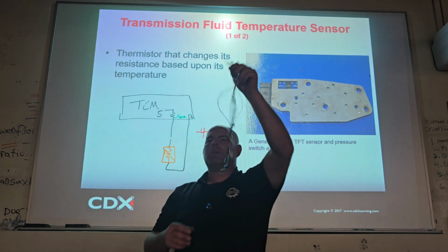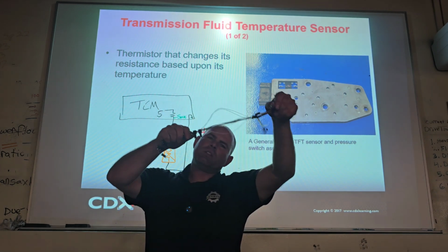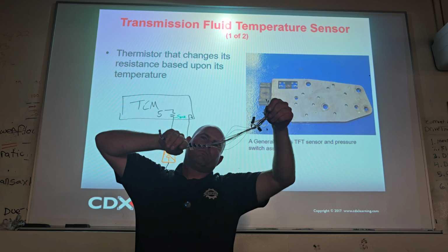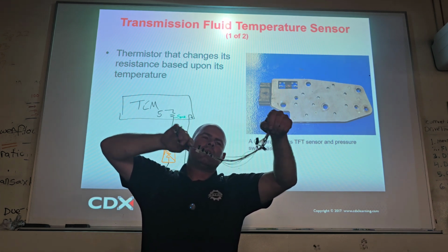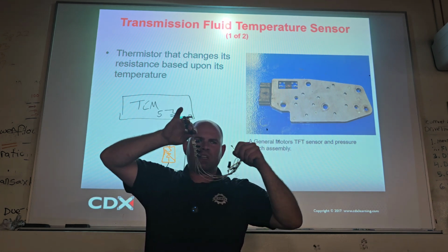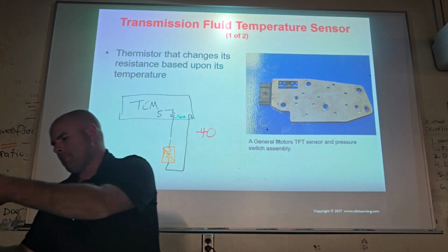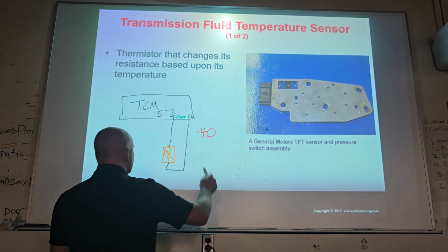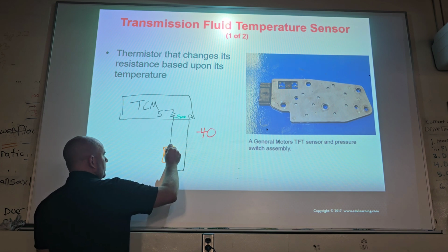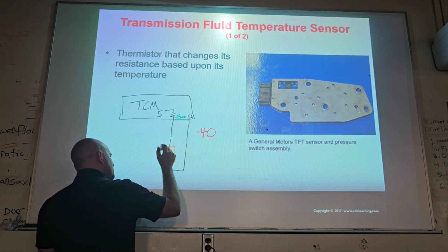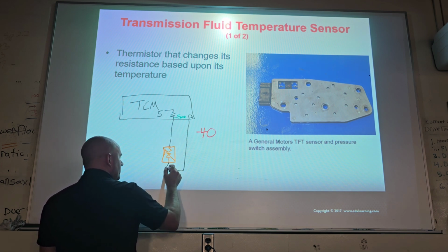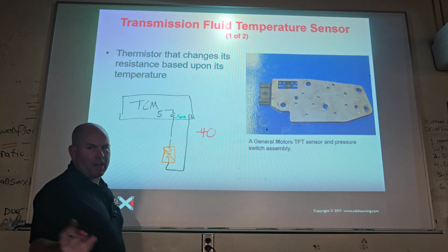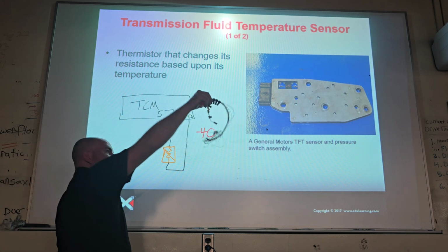So it could be a fairly minor repair, but to do this, you understand you're going to be in the valve body. Sometimes you have to actually pull the valve body off to get certain parts out. So either way, you mostly need to know, is it inside? And if it's inside, is it the sensor or is it one of the little wires? In this case, it doesn't really matter because they come together. It's an assembly.